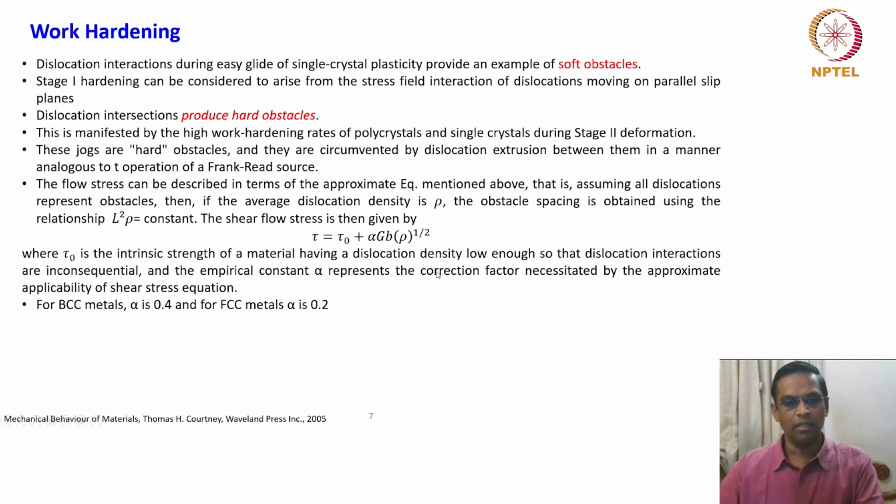So this particular hardening mechanism is purely based on dislocation interactions. Since we have already discussed quite a bit about dislocation interactions and also plasticity of single crystal and polycrystals a little bit, the concept here is the same. So that's why I just want to briefly mention it here. And this equation gives an idea how the dislocation density controls the shear flow stress.